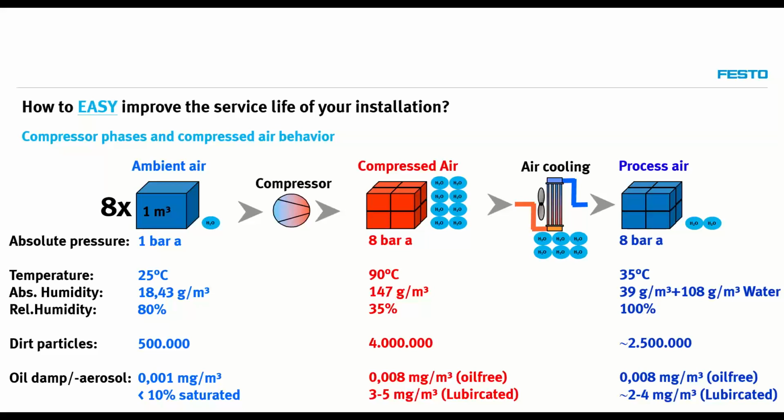Here we see an installation with the customer where the supply line of air to the filter regulator is filled with water of condensate. Maybe we will share the video with you, but the point is, it was a transparent tube fully filled with water, and you only saw some small air bubbles going through. And this water is having an impact on the performance of your equipment, because you're not having a pneumatic system anymore.